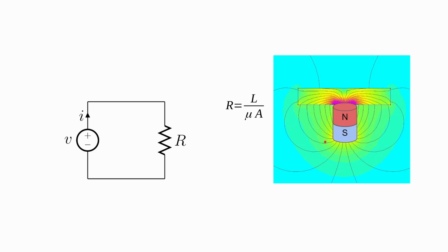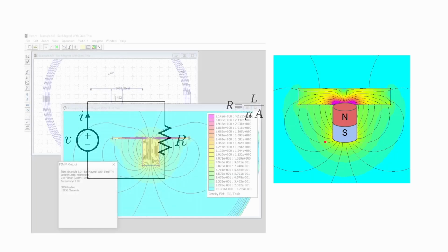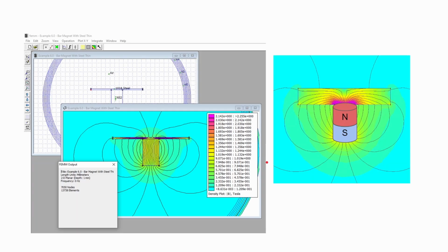For many magnetic problems, you have no choice but to switch to FEA programs to calculate these parameters. One of the best free ones is called FEMM. It's limited to 2D, but you can approximate a ton of systems quite accurately with this tool. I'm definitely going to make a tutorial or two on FEMM in the future.